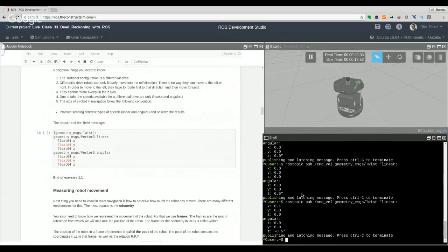But then how can I stop the robot when it's not receiving another command? Well, that's a safety measure that you should always implement in your robots, because your velocity control program can crash at any time. Imagine that you have the robot moving, and you have a very clever algorithm moving the robot around, avoiding obstacles.